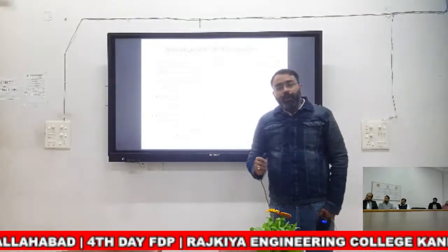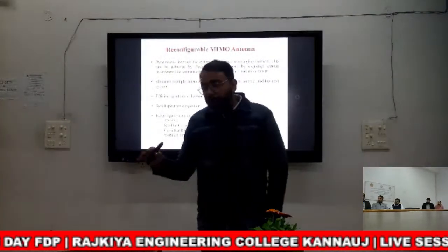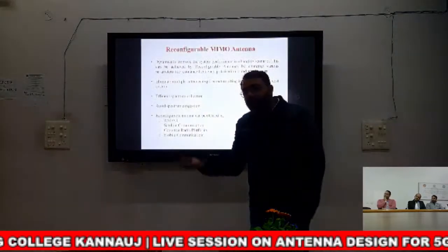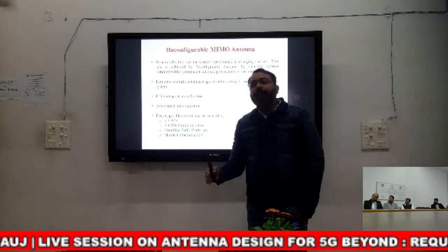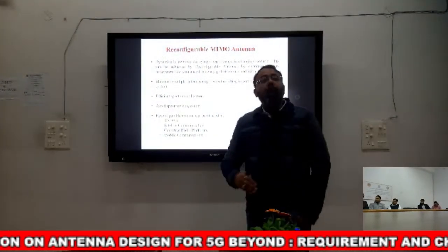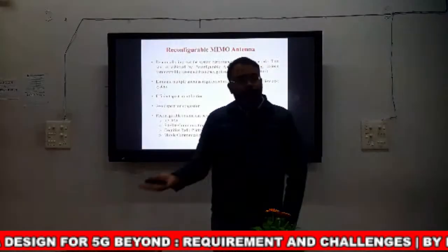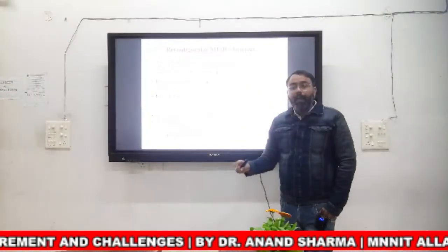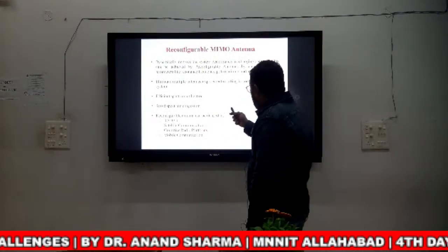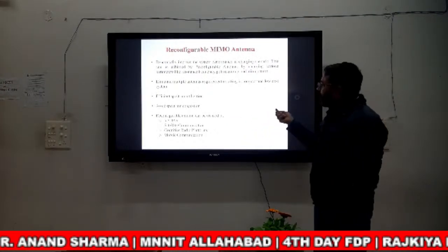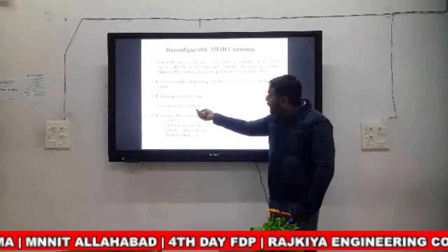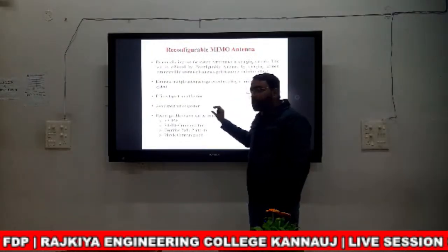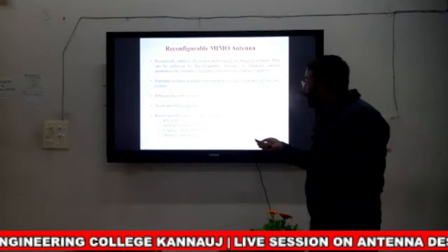Reconfigurable means the antenna has the capability to change its frequency characteristic, or pattern characteristic, or polarization characteristic, or a combination of frequency and polarization, or frequency and pattern, dynamically. It is widely used for efficient spectrum utilization, which is a part of cognitive radio. Avoiding spectrum congestion is also a use of reconfigurable antennas.